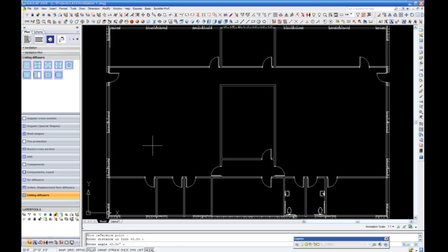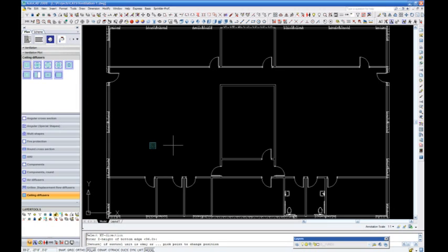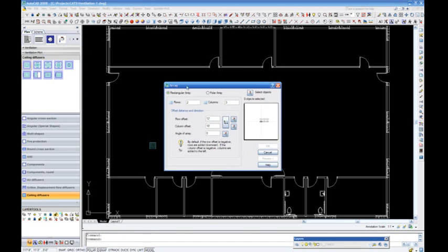The command bar is asking to select Start Point. Next command bar is asking for the Z elevation bottom edge. Our elevation height here is 96 inches. The software is asking to select the layer management for all diffusers. Our first diffuser is now placed.